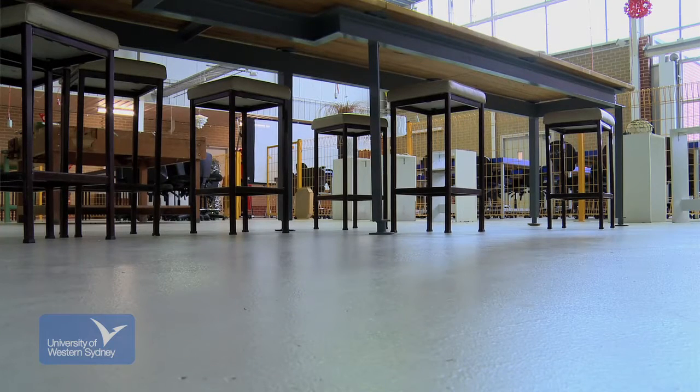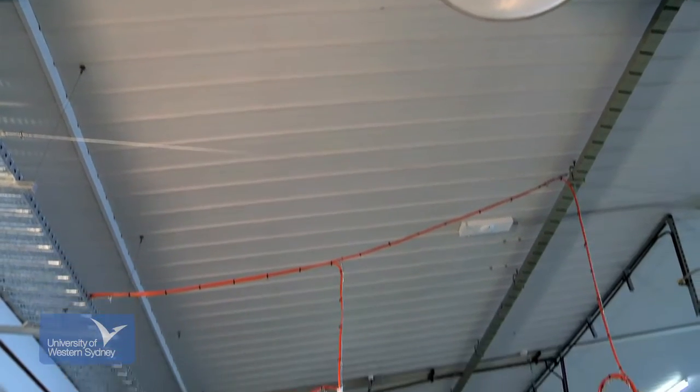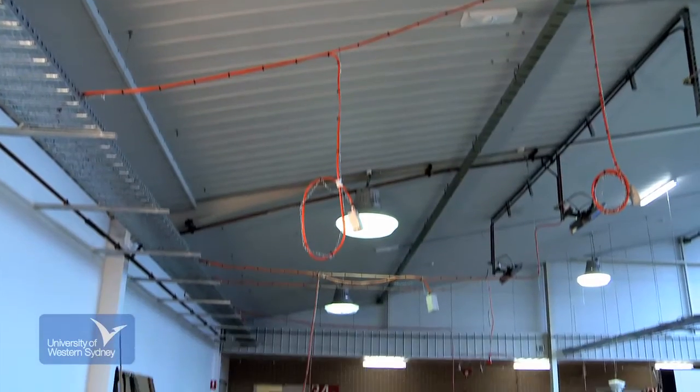The reverberations are recorded in hertz over the spectrum from 125 hertz up to 4,000 hertz. We're going to be seeing how many seconds the sound continues to reverberate. This is typical of a factory. Hard surfaces on the wall, hard surfaces on the floor. The only sound absorbing material is a perforated ceiling.